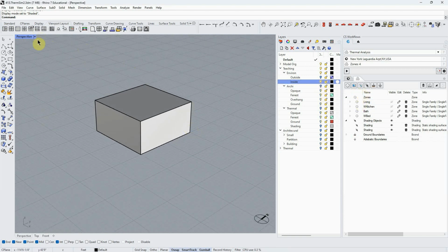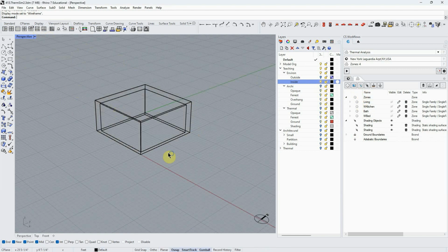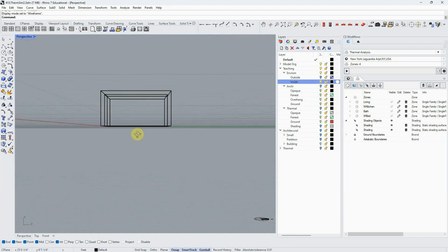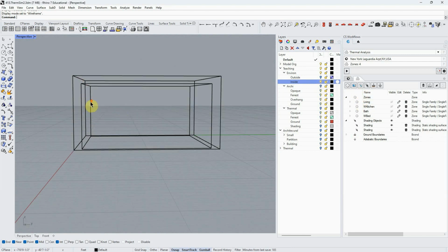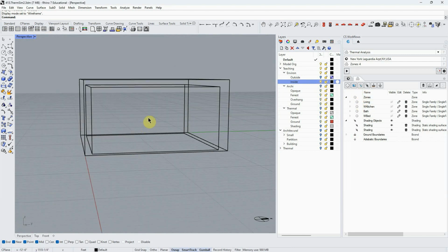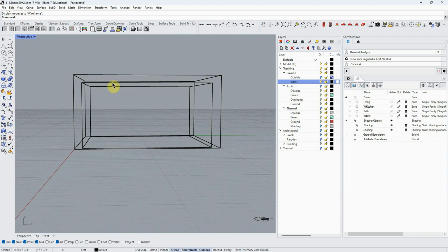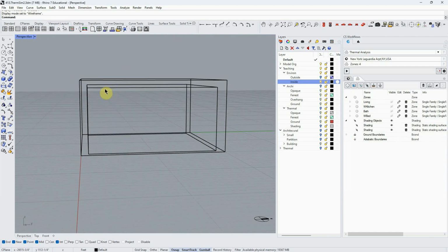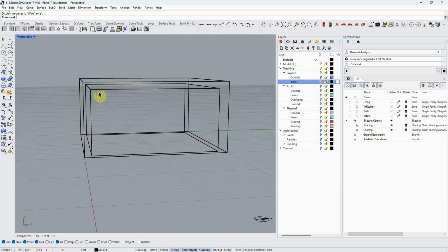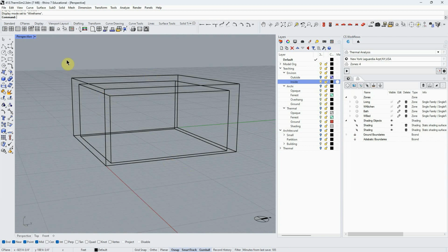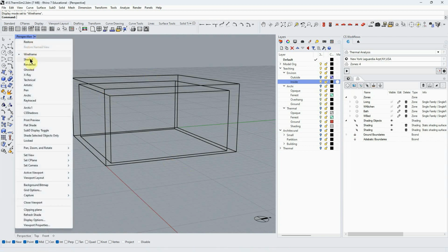And even this simple little box is an architectural model, not something we can use for a thermal simulation. That's because it has thickness. So we have an interior volume of air, the inside. We have a ceiling here, for example, and then there's an assembly that is more than just a surface separating the interior volume from the outside. That's great in an architectural model.